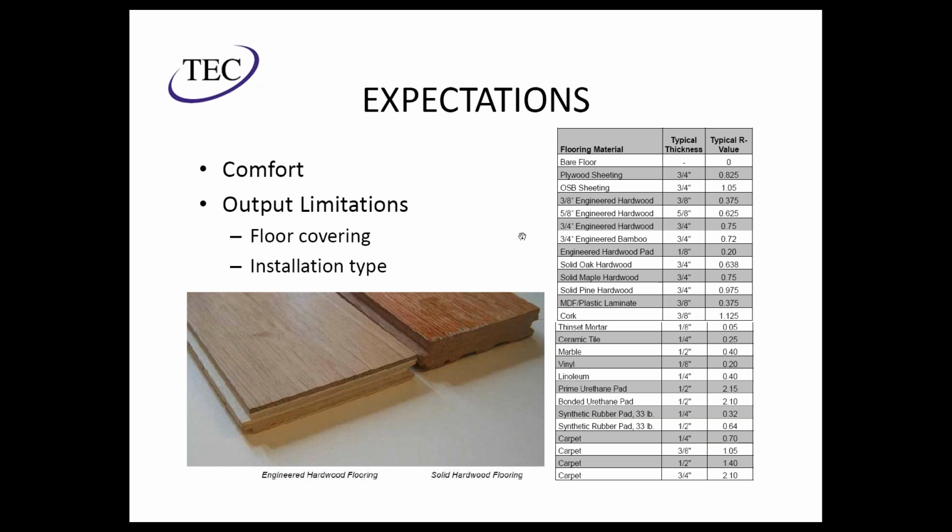One thing to note specifically, though, is what type of flooring they would like over the radiant system. The floor covering has a lot to do with the amount of heat that can be extracted from a radiant system, along with the amount of insulation that's put on the other side, since you still have to drive that heat up into the space. So if you're using a natural hardwood or cork, these materials are more insulative, especially carpet.